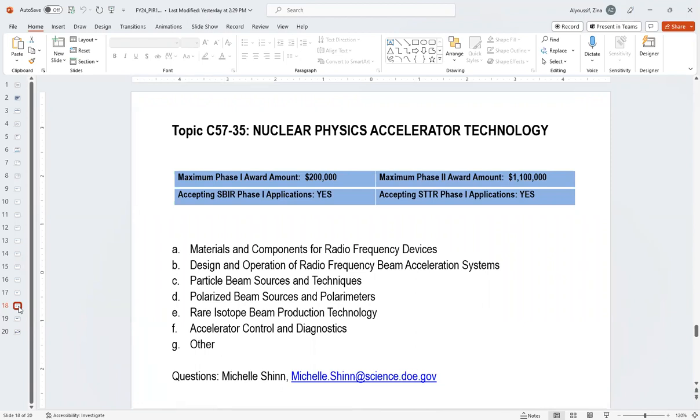So we know how to clean them. If we pull a cryomodule, a superconducting unit, out of the tunnel, out of the accelerator vault, and we take it apart in an ultra high clean room and all that, that's a well-established procedure. Cleaning particulates in situ would be a game changer and quite innovative. It might be much easier to do for, say, quarter wave cavities. It's hard to imagine how you would do it in an elliptical, but that's what we're looking to you folks for.